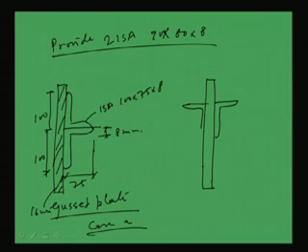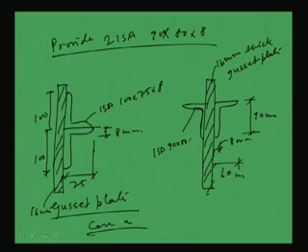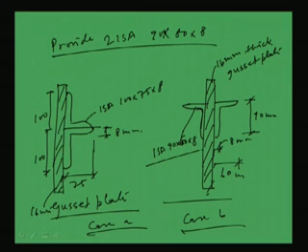So, if we place like this, this is a 16 mm thick gusset plate, this is 8 mm, this is basically 60 mm, this is 90 mm, the section is ISA 90 by 60 by 8, case B. So, for case B we can use angles of 90 by 60 by 8 to carry 120 kilonewton load, whereas for the other arrangement we need ISA 100 by 75 by 8 to carry the same amount of load.